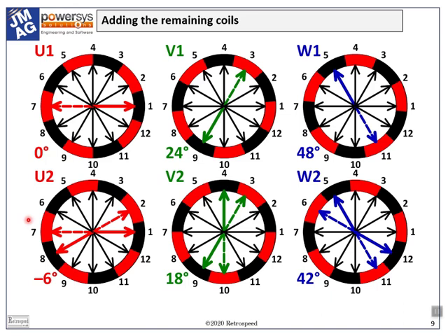Of course, if we have some experience of AC windings, we will know that plus or minus 15 degrees is not at all excessive. Indeed, the most common AC induction machines have a phase spread of 60 electrical degrees, which is twice what we're considering here.